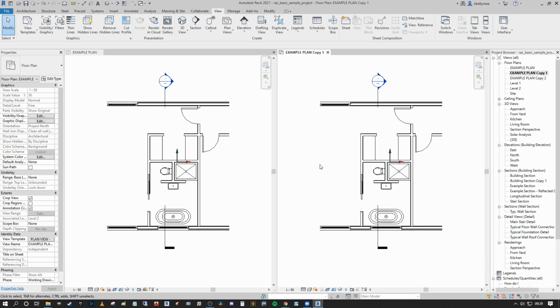The one reason that generally you would not want to do this is if you have a standard plan visual output that you want to apply to multiple levels, then in your view template, having that assigned as off means that you don't, let's say, try to replicate your ground floor presentation standards to your first floor, where the elements you want to present are likely at different levels. So that is the one reason on a view template you wouldn't have the view range active, but the majority of the time you could probably leave it active for exercises such as this. So that concludes number 4.